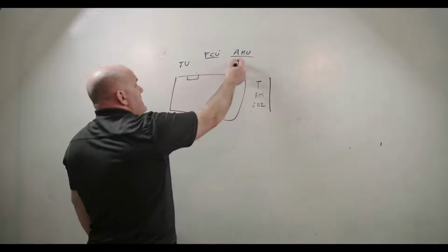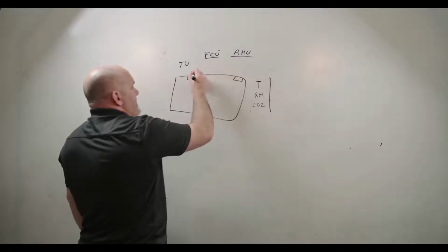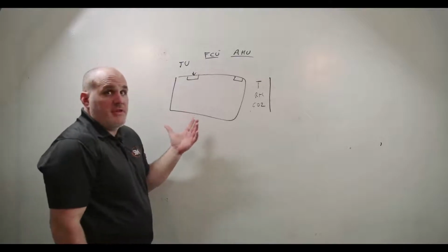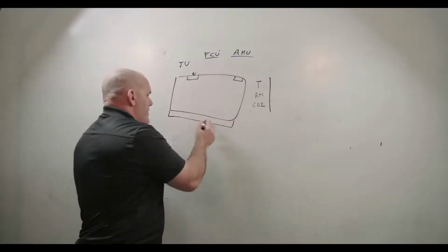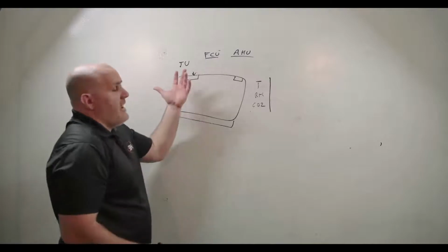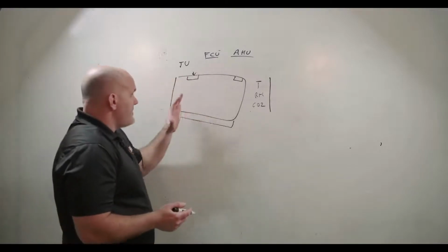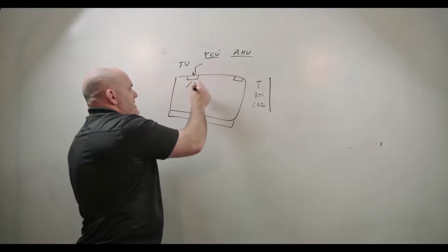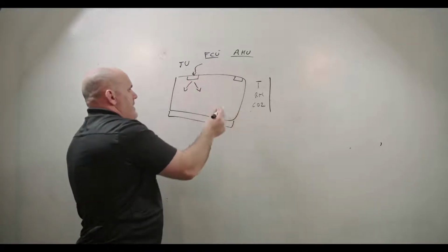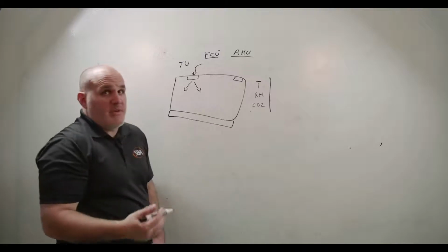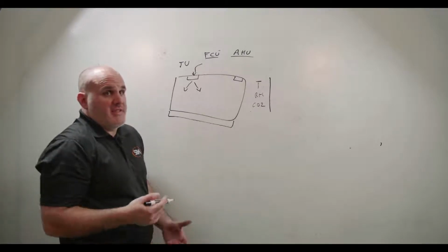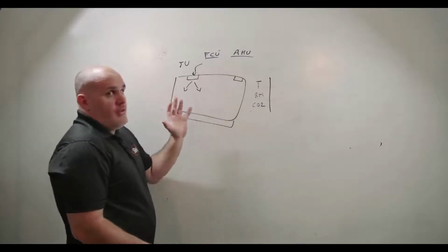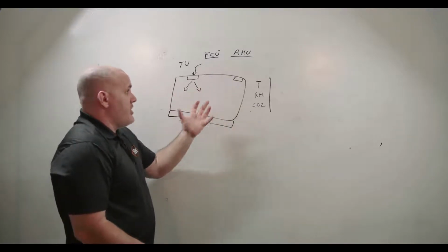Regardless, the air is going to flow into the space through a diffuser. This may be a floor mount diffuser in the case of underfloor, or we may have overhead diffusers. When the air is entering the space, it's supplying air into the space. CFM, cubic feet per minute, is the measurement we use, at least in the United States, and we have a cubic volume in height, width, and length of the space that we are trying to fill with air.